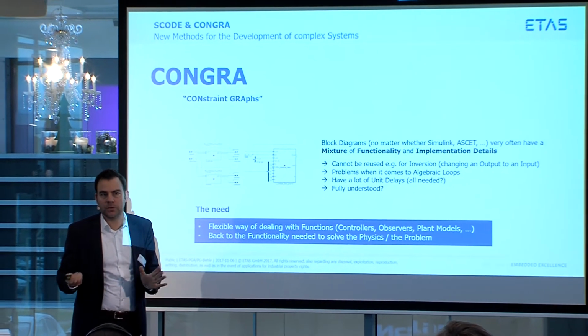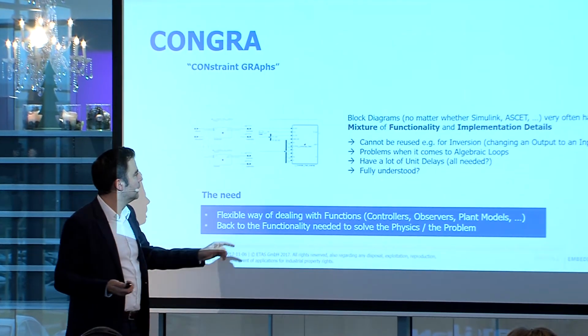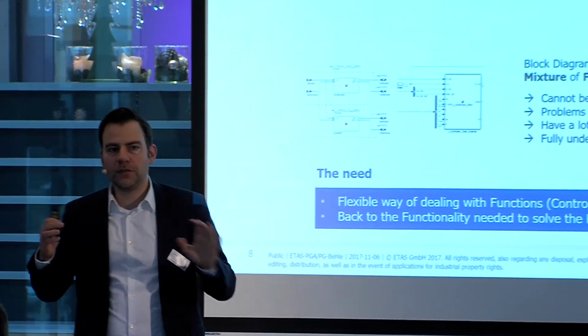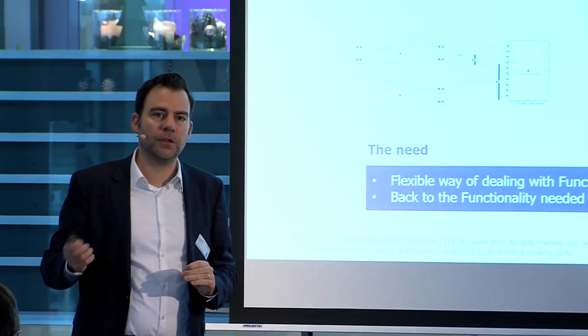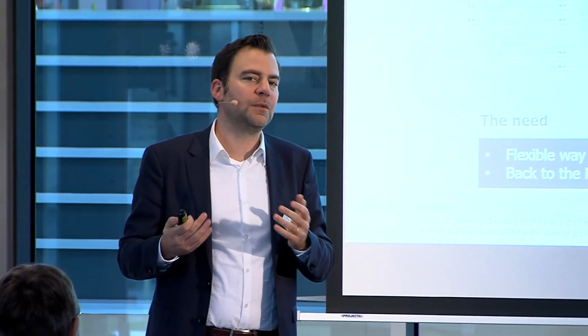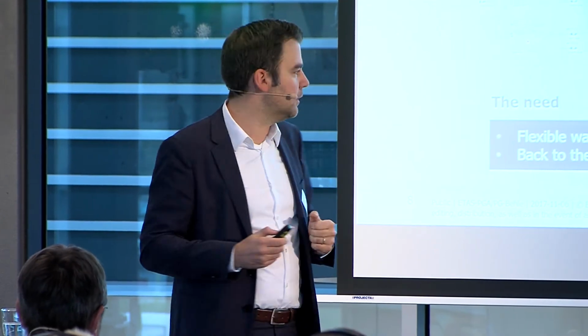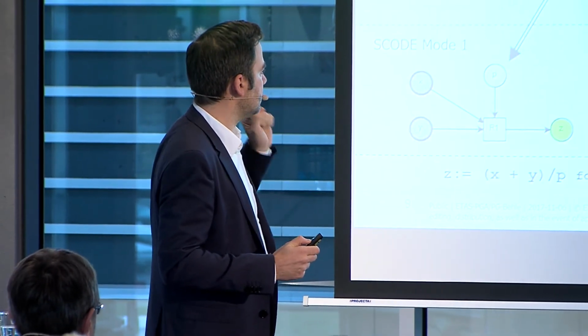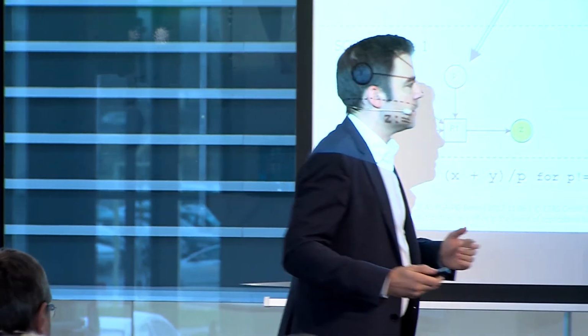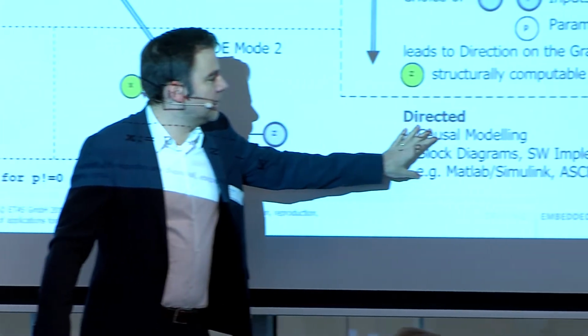We cannot implement them locally. That's what you would want to do as a control engineer. And we have algebraic loops. That's a huge problem. Warning, algebraic loop, what can you do? What you usually do is you introduce a unit delay, and you do not really know what kind of dynamics you get from there. So we said, let's do the same as in Escodi.